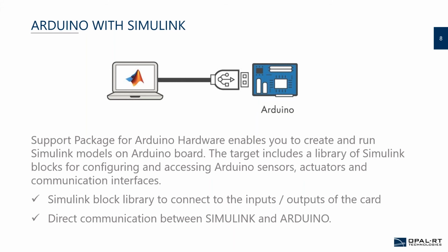You can also use your normal MATLAB Simulink blocks, for example your sensors, your scopes, your displays, and your cascades, and so on. There is a Simulink block library to connect to the inputs and outputs of the card, and you can have direct communication between Simulink and Arduino.